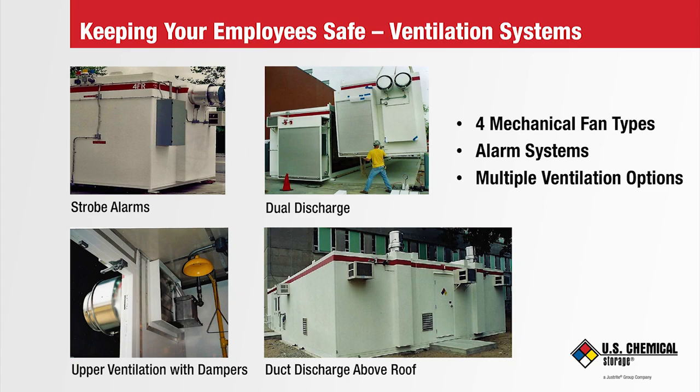In the lower left-hand corner, you've got an upper exhaust fan outside a vent opening. Inside the vent opening is an explosion-proof motorized louver. At a predetermined temperature setting, the louver will open and the fan turns on, pulling hot air off the ceiling. Supposedly a poor man's air conditioner. But in some cases, there are stored chemicals whose fumes are lighter than air, and a chemical temperature could trip their removal with this system.